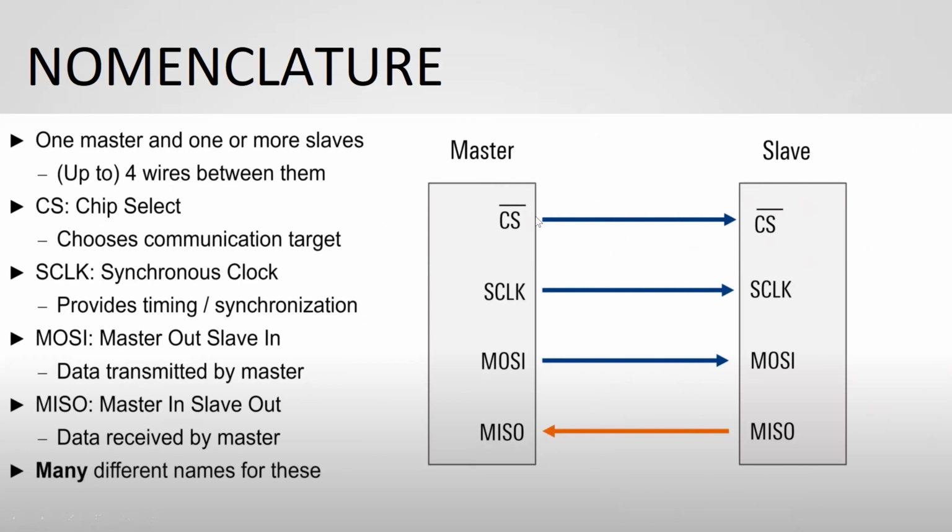Usually chip select is a low trigger, right? Whenever the device is not in function, it will stay always at 5 volts, so active high. Suppose the master wants to configure any of the slaves, at that time it will simply pull the line from active high to active low, and makes the slave enabled to respond to the master.